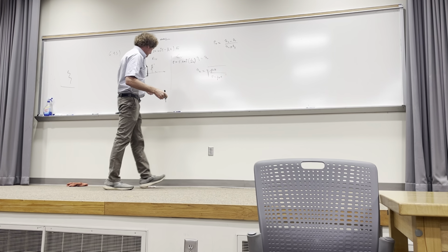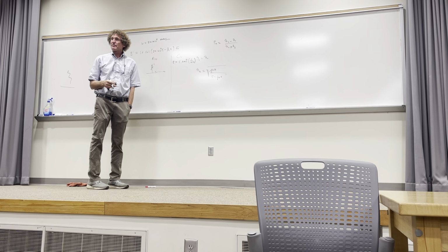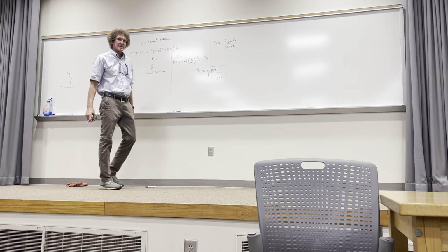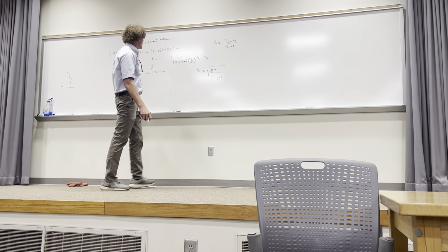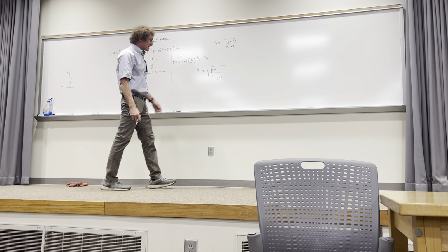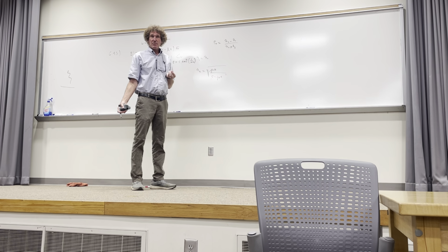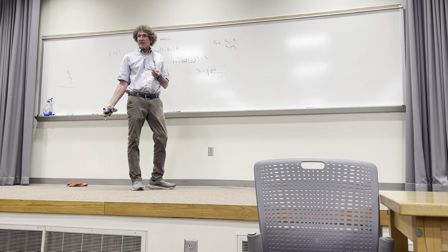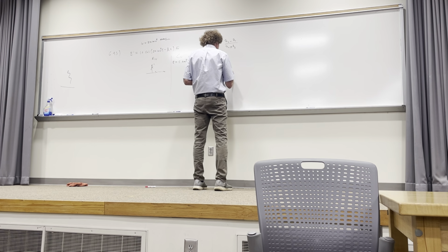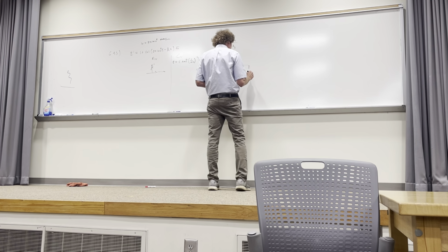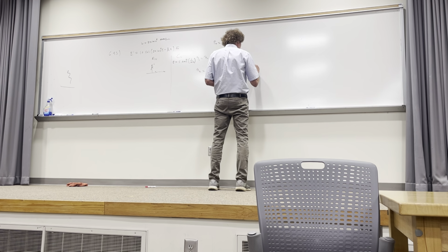And how am I going to modify that? Probably, I don't have to. Anybody? Let me ask you this. Sigma is 5.8 times 10 to the 7th, right? Omega is 2 pi times 10 to the 8th, and epsilon for copper is just epsilon naught, right? So this is almost non-existent. Do y'all agree? If you want to put it in, go ahead. It's not going to matter. But this is about equal to what? It's about equal to the square root of omega mu over sigma at an angle of 45 degrees, or e to the j pi over 4.